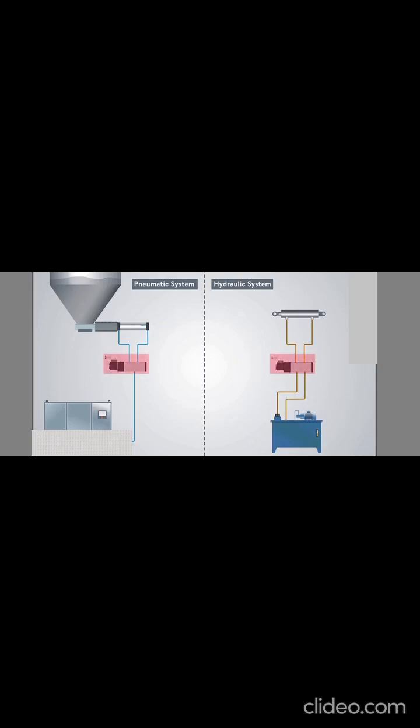Directional control valves are used in pneumatic and hydraulic flow control systems. So, there are pneumatic directional control valves and hydraulic directional control valves. Sometimes, the hydraulic directional control valves are called spool valves. As we're talking about the basics of DCVs in this video, and there's not much difference in their working principle and symbols, we develop our example based on a pneumatic system. And of course, if you learn one of them, you can easily learn the other.